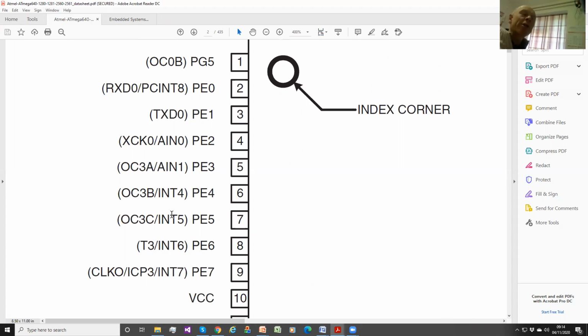That's just one timer. So you've got 6 timers altogether. Some of the timers can produce 3 wave patterns. Some of them can produce 2 wave patterns. So in total, you can produce more than 12 different servo control signals or pulse width modulation signals from the one microcontroller, which is more than most robots need.